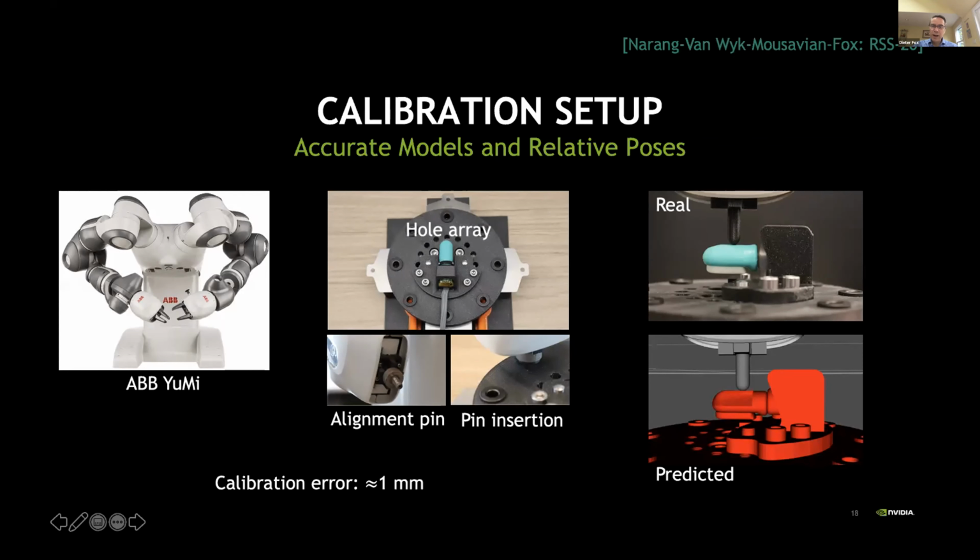Then, if you look here on the right, what we can do is 3D print an indenter, like in this case, this black 3D printed device. You can now start poking the BioTac sensor. That poking will also be measured. You get the BioTac electrode measurements, but also the force torque measurements from the 6D force torque sensor. And because everything is 3D printed, we also have a full 3D shape model for everything that's going on.